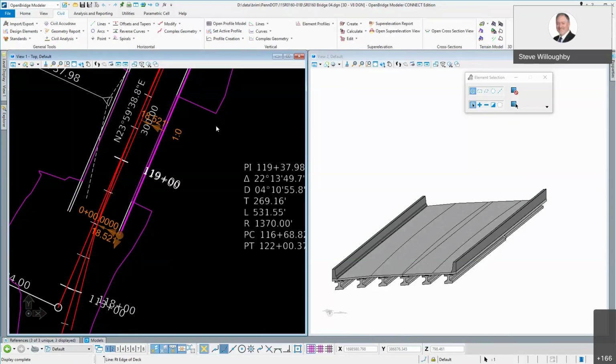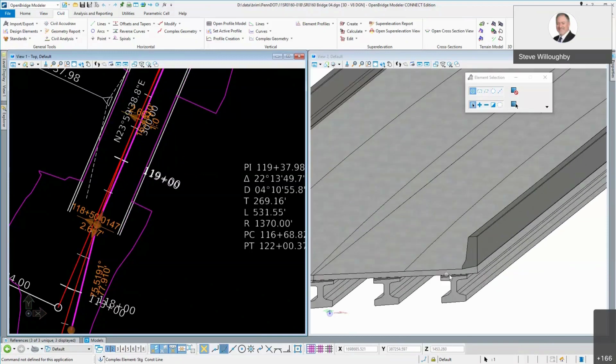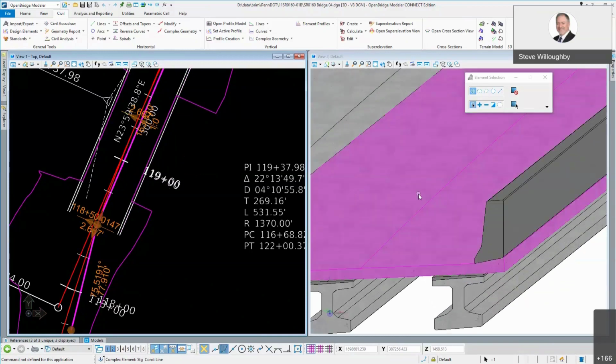It's just adding the drafting, like adding a MicroStation line. What happens is we put properties there. So you can have some intelligence, where it would react if the alignment changes or something like that. That's why I defined this line first, and then everything else relative to it. So if I change the offsets for this line, then all of these other lines are going to move with it. And I actually noticed some things I had wrong even in the template here,